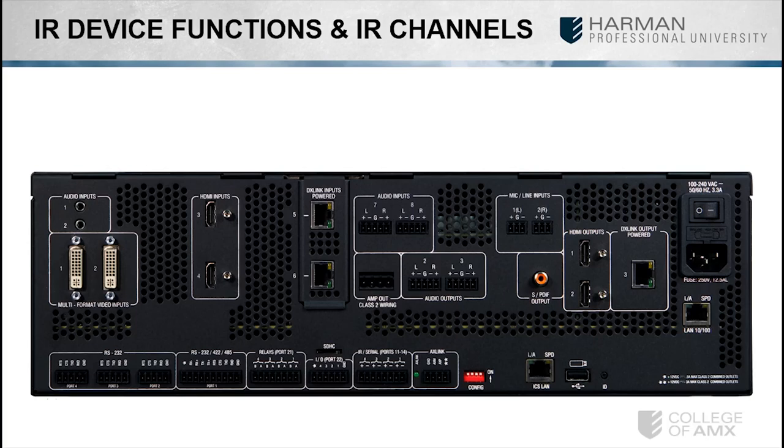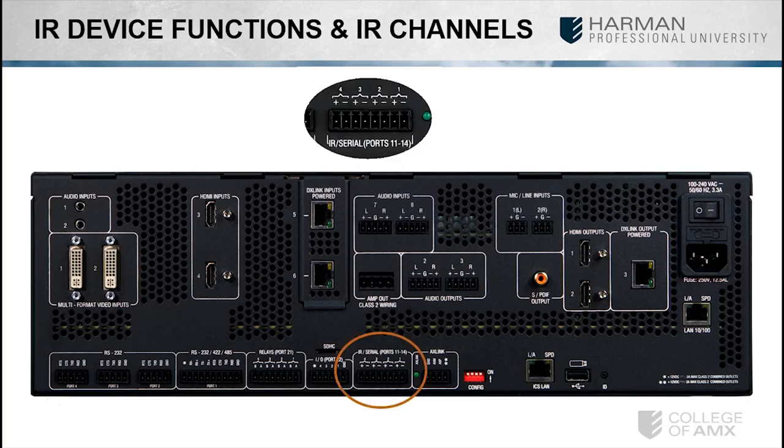As discussed earlier in the tutorial, each IR file must be uploaded and associated or mapped directly to the IR port on the controller that is physically controlling its corresponding device. Remember the DPS triplet? If the IR device to be controlled is a DVD player connected to IR port 1 on a DVX2255, then the device identifier will look something like this: DV-DVD equals 5001 11 0. A subsequent IR controlled device, for example a set-top box, could then be connected to IR port 2. The device identifier for port 2 would then be DV-STB equals 5001 12 0, and so forth.